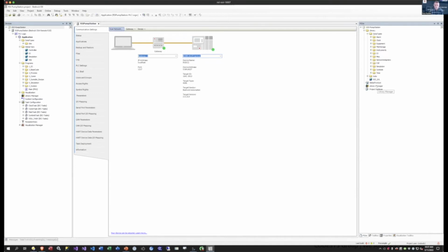And I've done specifically that on well sites in the water industry. Every well site is pretty much identical. So I keep all of my code over in the POUs. On the right-hand side are all of my devices and their global variables. And then I just call the same programs over and over for every device. Really, really handy feature. Now, of course, you can also use a library to do the same thing. And Alex talked a little bit about that. So those programs could also be placed in a library, and then you could link to the library in your program as well.